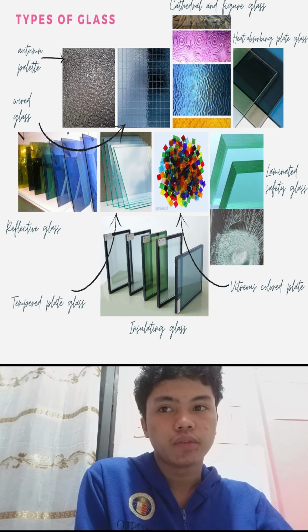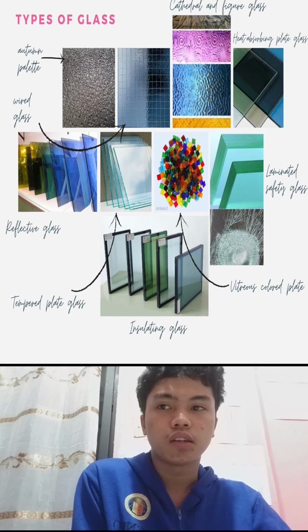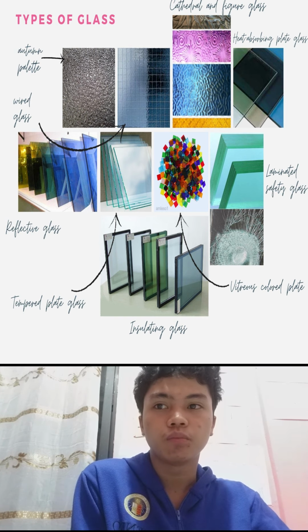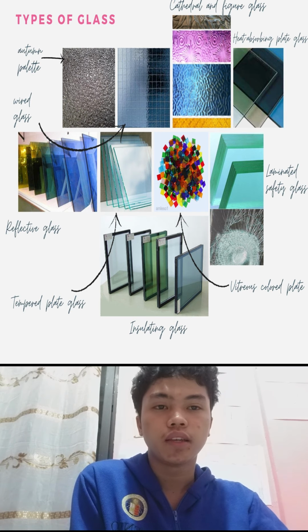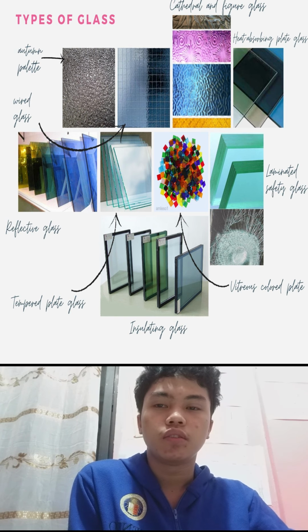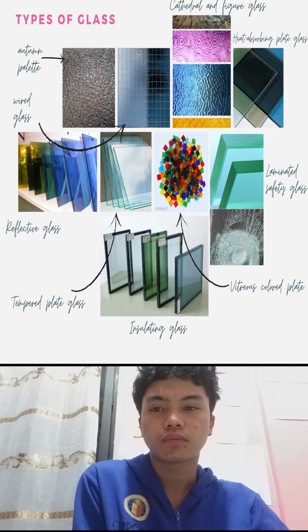Wired glass can be tinted by aerosol or electricity. Common colors are golden yellow, green, light blue, and violet rose. Thickness is 6 mm, 6.5 mm, and 7 mm. It is widely used for windows, doors, and partitions.